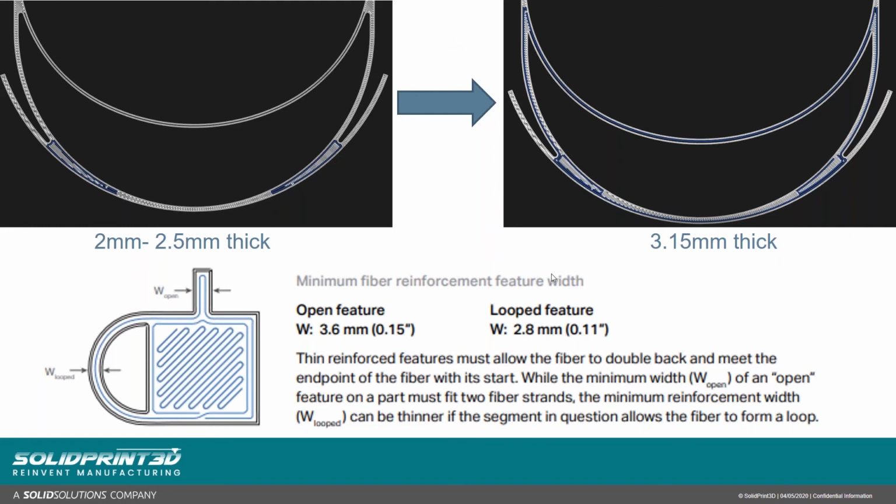So from this, we can actually go back in SolidWorks. We could do a few changes, as we know that we can actually get one loop round. If it's at 3.15, we could decrease that a bit further. We could reduce the amount of material, and therefore speed the print up a little bit further. All these changes we can do are all down now to the printer, rather than thinking about just the design itself. That's effectively what we've been trying to discuss throughout the entirety of this webinar.